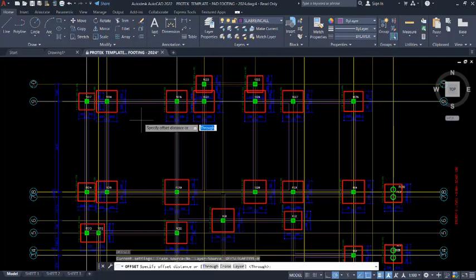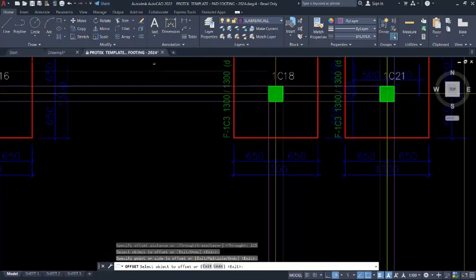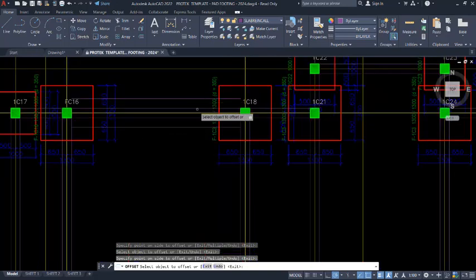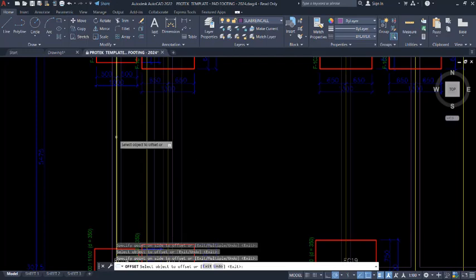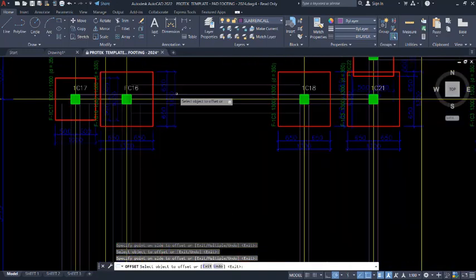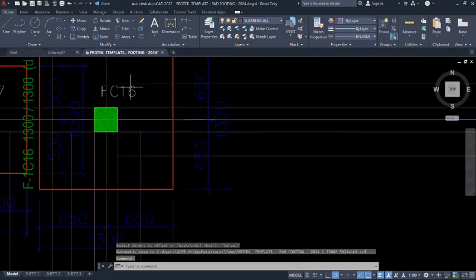Go on the keyboard, enter for offset, and then you have to do 5 right there, enter, and then just do offset this way. This is working space right there, and then downward, this is also a working space. So this is what you're going to do in all of these column provisions that have to provide a working space for the foundation trench, successfully.